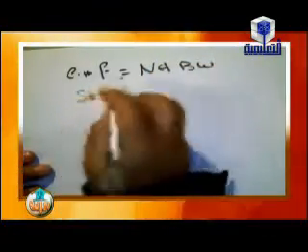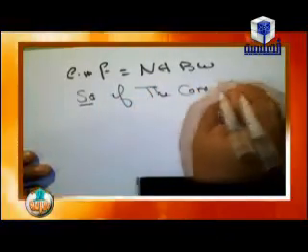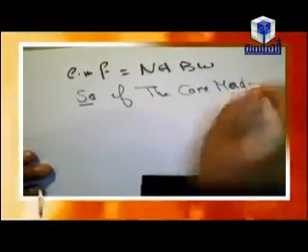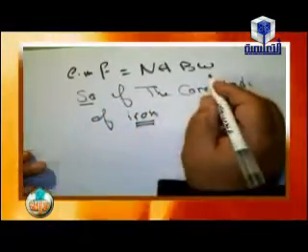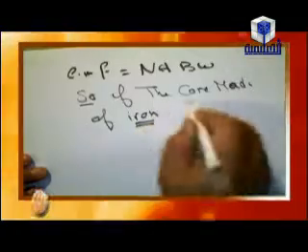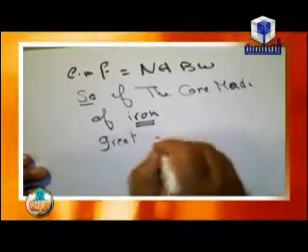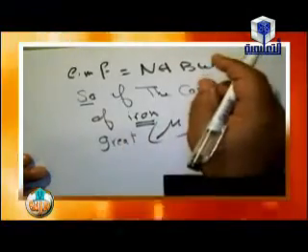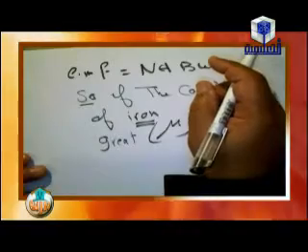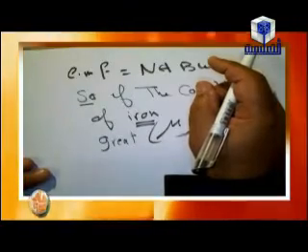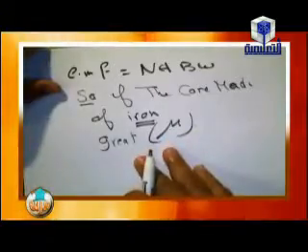So if the core is made of iron, because the iron will concentrate the magnetic field, because iron has great magnetic permeability, mu. So the core of the coil of the dynamo is made of soft iron, because soft iron concentrates the magnetic field, and iron has great magnetic permeability, so it increases the induced EMF in the dynamo.